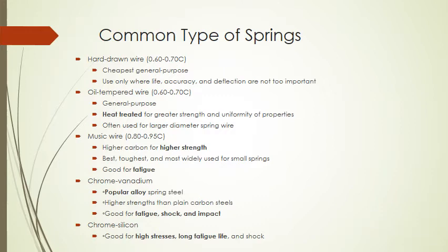But for very specific purposes, like some vibrational purposes and some shock purposes, we should have a spring that has much higher strength, high fatigue properties, and the important property of toughness. Toughness in springs leads to the property of absorbing high shock and vibration.